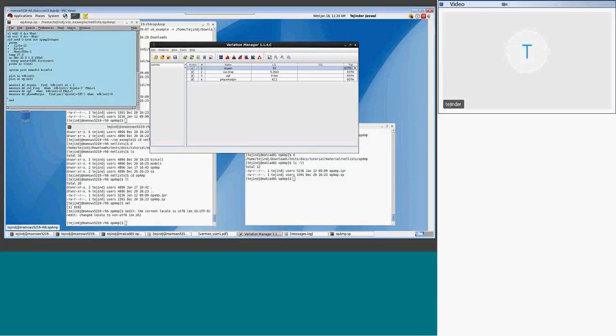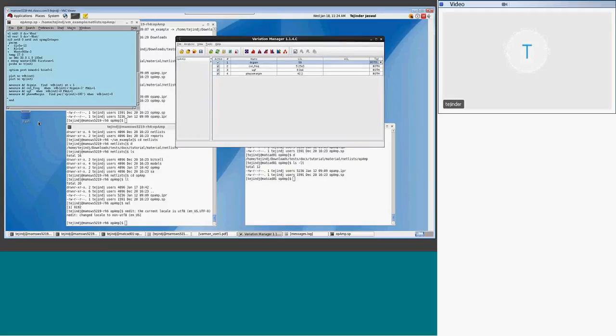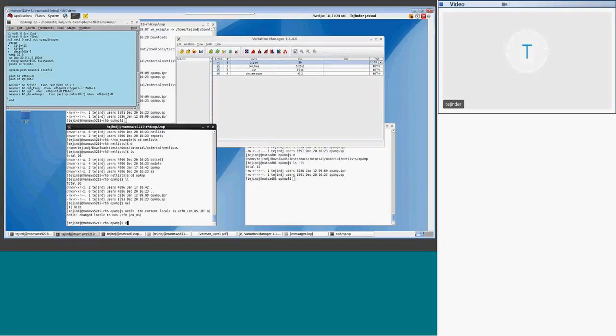But if you fix LSL or USL or both, it gives you the samples that are inside and outside. It will indicate, for example, that maybe 9 samples simulated are outside your limits. For example, you can compute a yield like this.